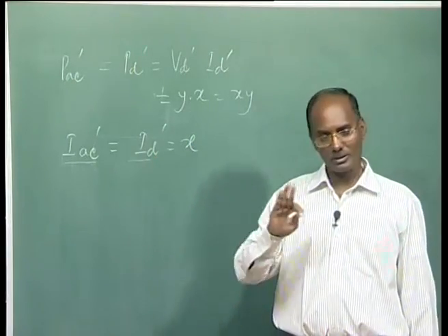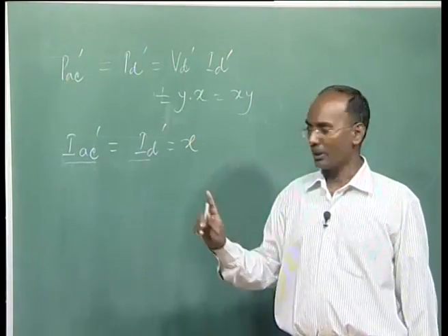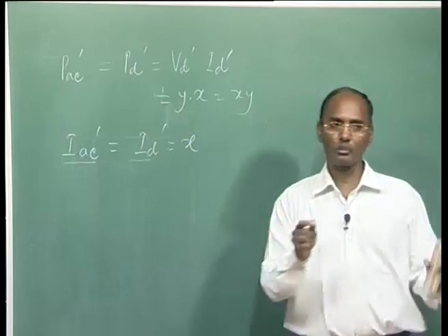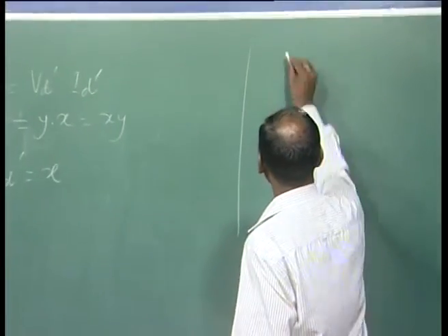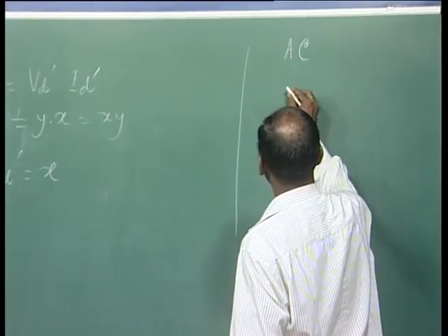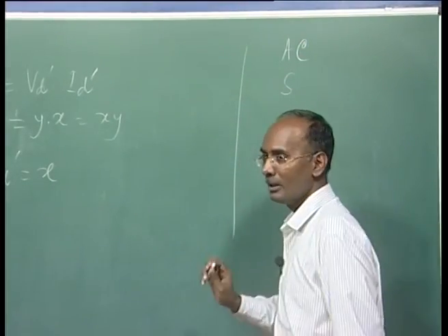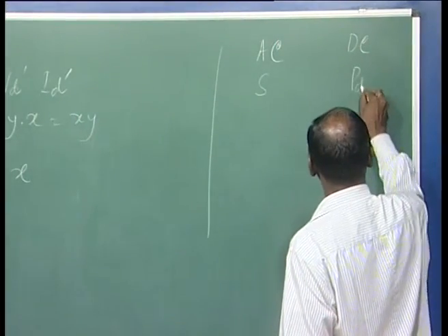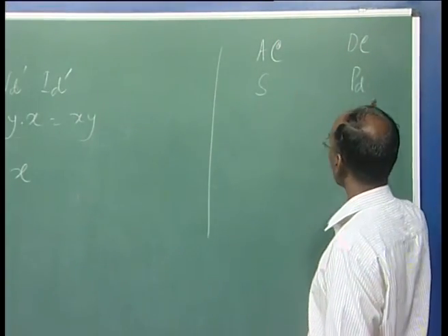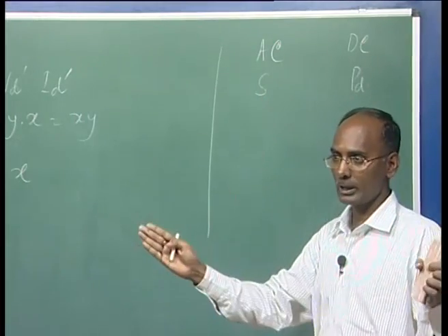It is not guaranteed, it is not necessary, because you know what voltage we are taking on the primary side, what is the base value? If your AC side base is power, and on the DC side we have the same power, the PD, the base value is the same on both sides. Power is the base on both sides.